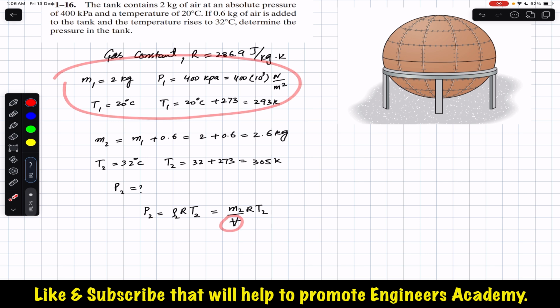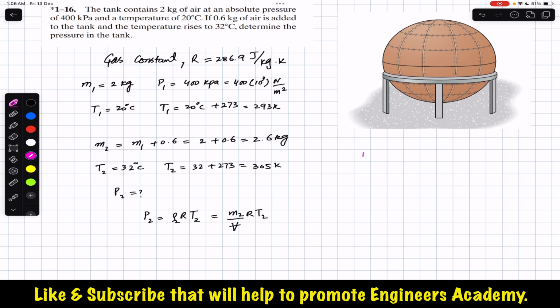So from the initial data we can say that using the same equation, P1 is equal to rho 1 R T1, and again rho 1 will be M1 divided by the volume of the tank, R into T1. So rearranging this equation we can say that volume of the tank is equal to M1 R T1 divided by P1.